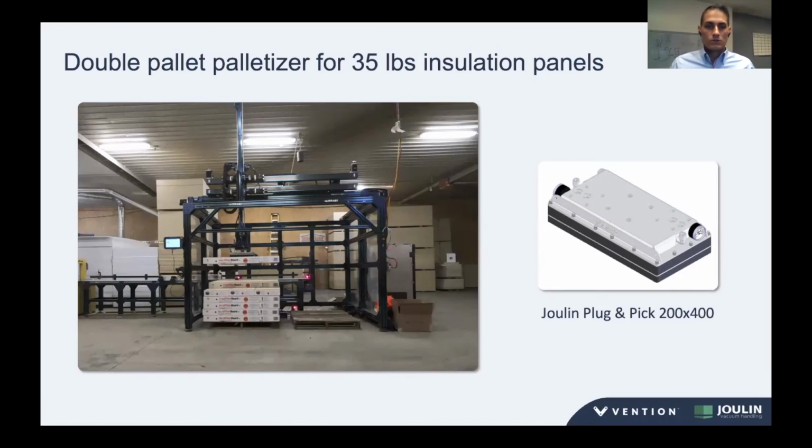There's actually two zones split right down the center of the gripper, so if you had a box that was slightly less than 200 by 200 or even 200 by 200, you could pick both of those boxes and then palletize them individually just to create your patterns how you want on the pallet. I mean, it's really a great system. You've got two dry vacuum gauges there, so you can tell the vacuum in each zone.